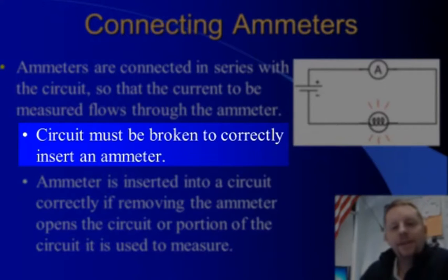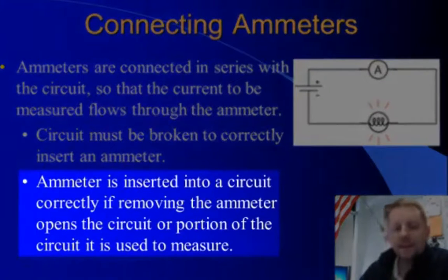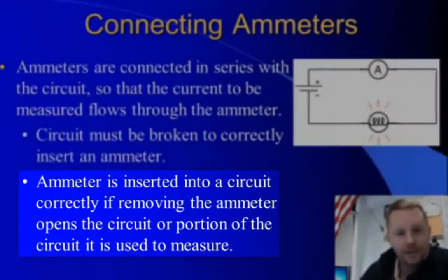If you can insert an ammeter without breaking the circuit, then you're doing something wrong. If you remove the ammeter, the circuit, or that portion of the circuit you're trying to measure, should stop functioning. It should have an open.